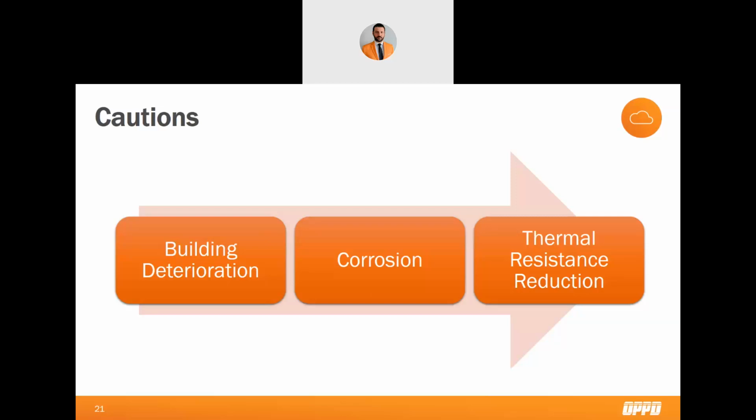Insulation ends up in places in our homes that are prone to moisture if proper air sealing isn't present. Moisture can ultimately reduce the thermal resistance of insulation and potentially damage the insulation.